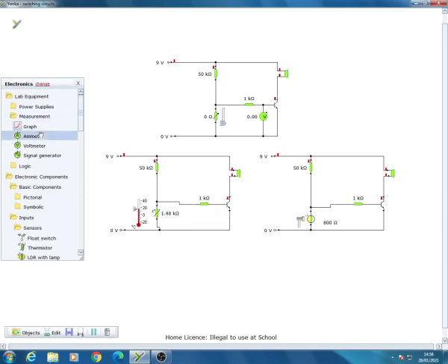Now the reason for that again is because the voltage across the base is suddenly going to 0.7. You can see at the moment that's 20 degrees, and at 20 degrees the voltage here is 0.2. As the temperature drops, the resistance here is going up and the voltage here is going up. So we've got to 0 volts there and going down to about minus 10. So at about minus 10, all of this switches on.